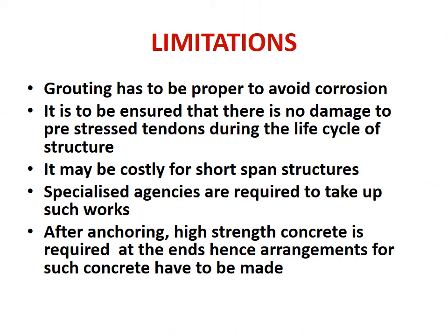Then there are a few limitations, and grouting has to be proper to avoid corrosion in bonded PT slab construction. And it is to be ensured that there is no damage to pre-stressed tendons during the life cycle of the structure. Suppose you want to hang something during the maintenance stage, and if you damage the tendon which is already pre-stressed, then that may result in its failure, and then an accident may occur. So it has to be ensured that there is no damage to pre-stressed tendons during the life cycle of the structure.